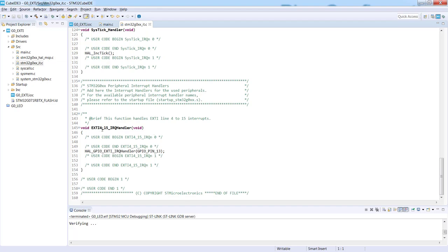It is called EXTI. In the Cortex-M0+, which is the base core for this microcontroller, some external interrupts are grouped together, and our number 13 is within the common vector used for channels from 4 to 15. If you are interested in more details about the structure of this external interrupt peripheral, please refer to the separate online training which is available on our webpage. Now we will focus on handling the interrupt.